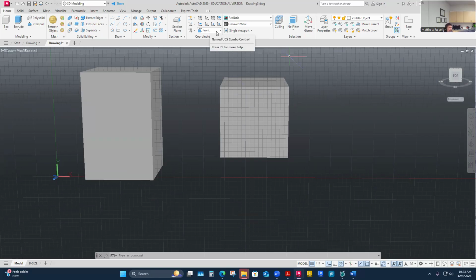So I like that these are front, tops, rights, and lefts because sometimes I draw things and I start them and I think of them as the front view. Well, then I would want to toggle on the front view grid plane and start drawing it in 3D on the front view grid plane. If my view is going to be a top view, then I might want to start on the top view grid plane and draw my 3D. This is going to matter more when we go to actually throwing stuff on a drawing and dimension it.